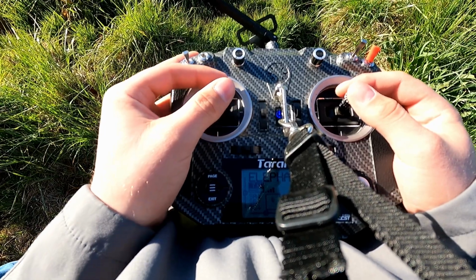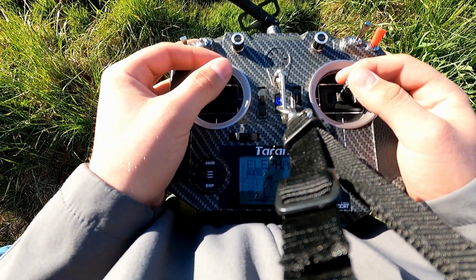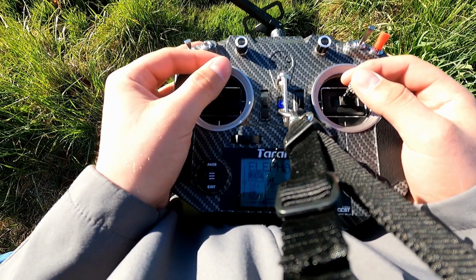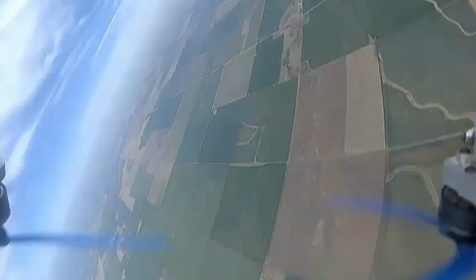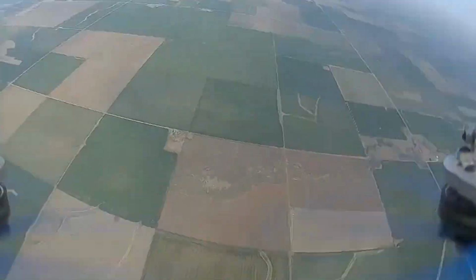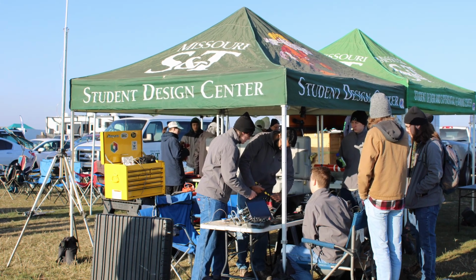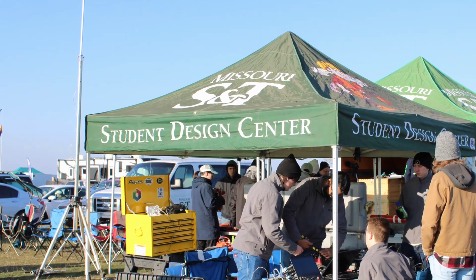All right, so our drone is controlled with manual input through ELRS, which is a low latency, high range device. We've actually used this in not only this competition, but in previous years in the Argonia Cup, where we had it connected to the transmitter while it was in a rocket going up to 10,000 feet, and we didn't have any connection issues then either. It's running 2.4 gigahertz, and our telemetry radio we're also using has 915 megahertz, and we're running about 500 milliwatts on that.